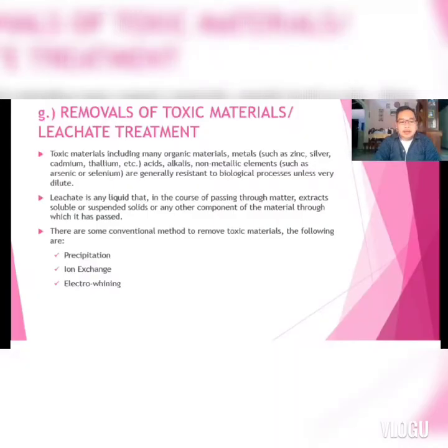And next is cementation. Cementation is another type of precipitation method implying an electrochemical mechanism in which a metal having a higher oxidation potential passes into solution, for example, oxidation of metals into ferrous, to replace a metal having a lower oxidation potential. Copper is most frequently separated by cementation along with noble metals such as gold and silver.